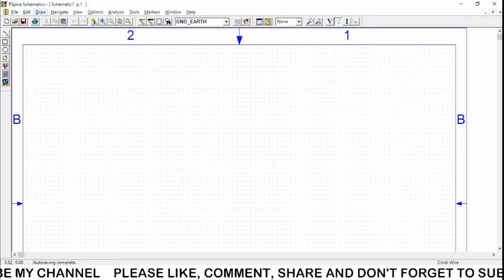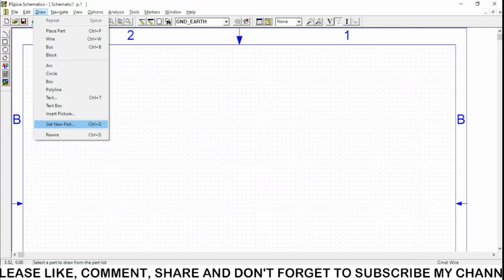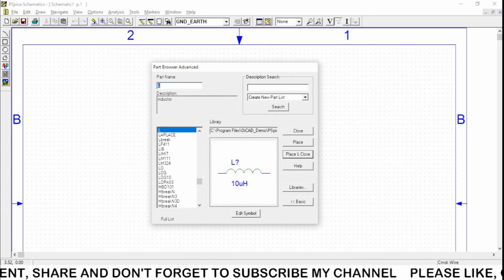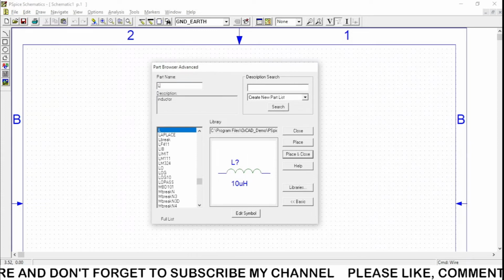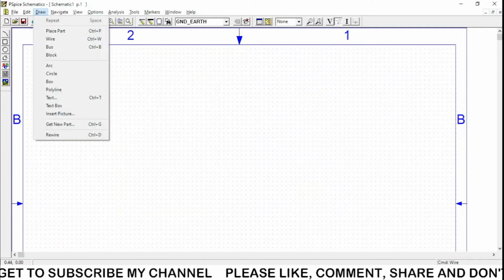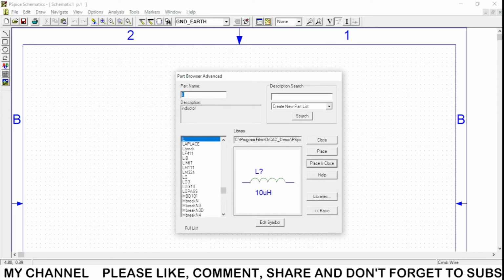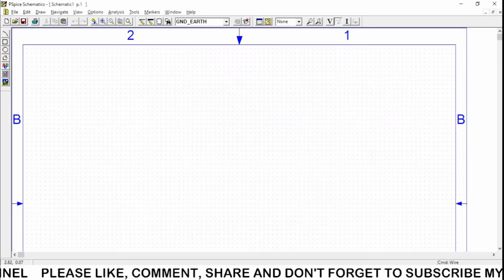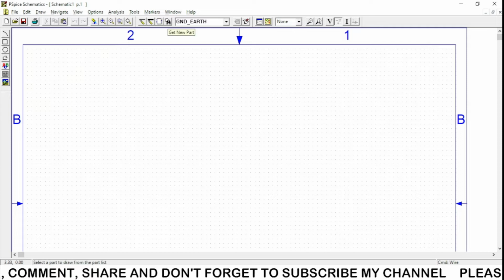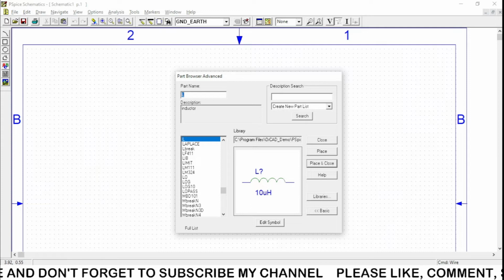For this purpose, we need to go to Draw, then Get New Part, or there is a shortcut, Control G, or there is a button where you can take the new part. From that you can take the components. So what we need to take is VDC.